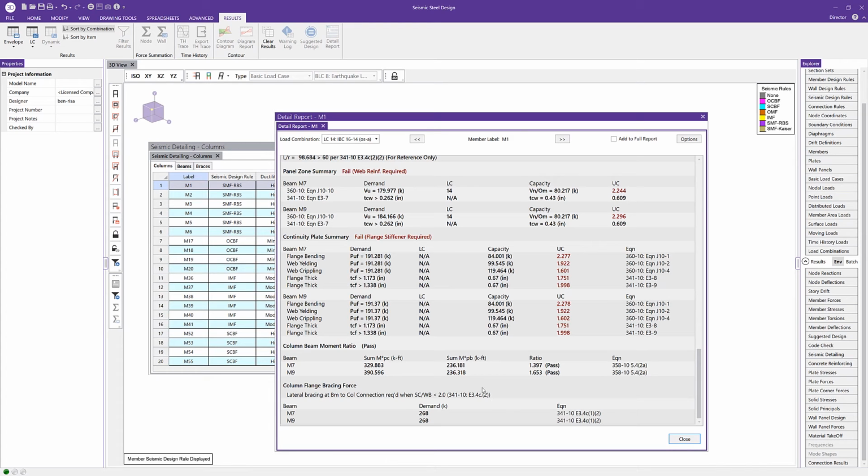our seismic system. Maybe we've just determined that in this case, the special moment frame isn't working, or this tells us that we need to upsize the member, right? We need a larger column in this case.